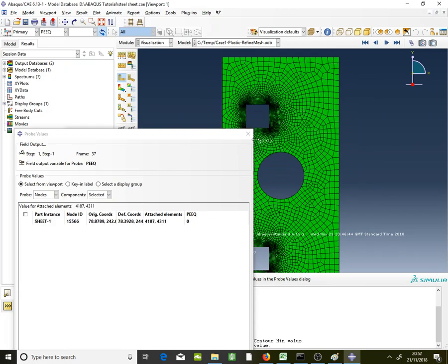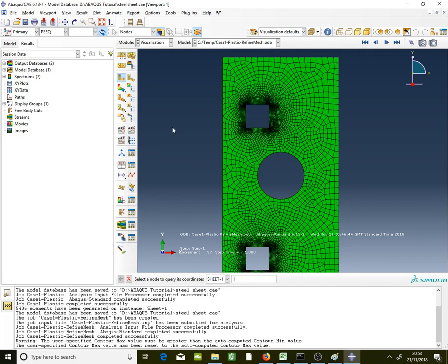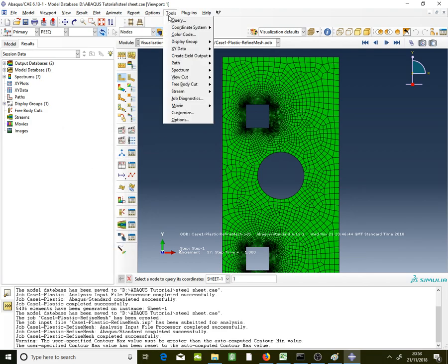Now we close it. If we need to find out the load displacement relationship, so as your load applied, what, and as the displacement applied, what is the load or reaction forces, in order to find out the ultimate load capacity of this plate. So please follow me in these steps. Close here, add your result, go to tools. So firstly, let's find out the forces, the reaction forces.